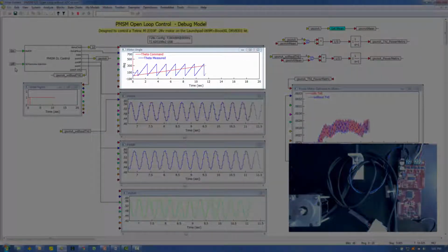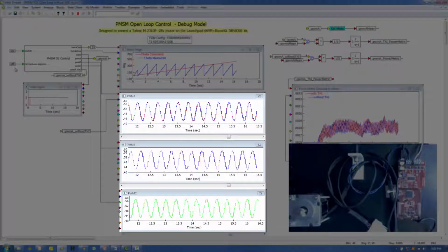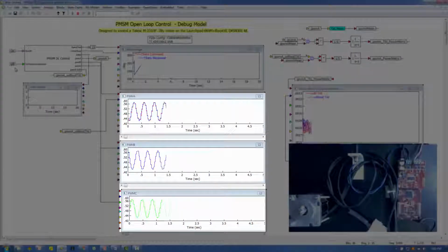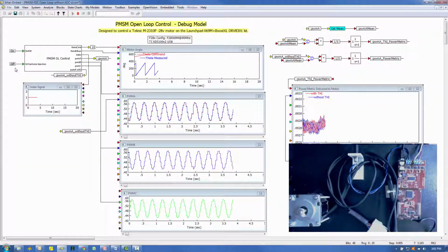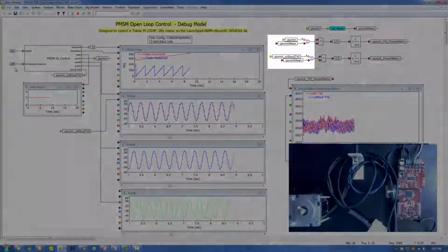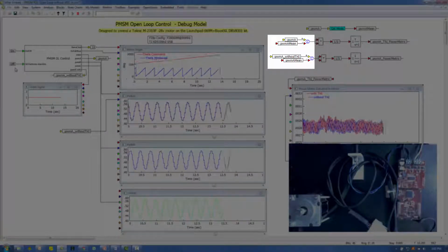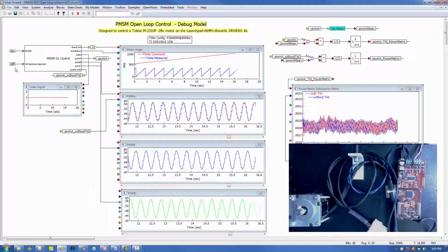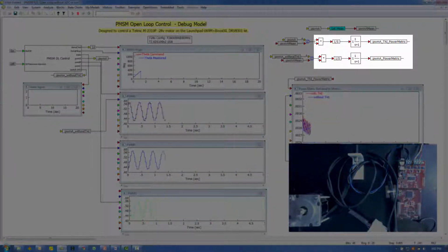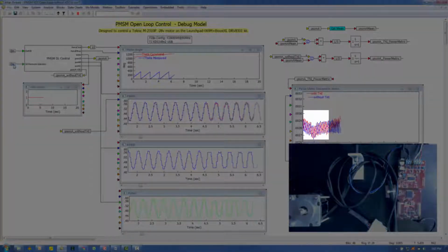The top plot displays the motor angle and the open loop angle command. The lower 3 plots display the PWM sinusoidal waveforms. The quantization is due to the bandwidth limitation of the JTAG interface we're using. On the right, I've calculated the mean value of PWM-A. Then I've shifted the 2 PWM-A signals, one without THI and the other with THI, to have a 0 mean value. The energy of each signal is calculated as the integrated square value, and a power metric value is estimated using a lag filter. Observe that when the THI is off, both power metrics are identical.